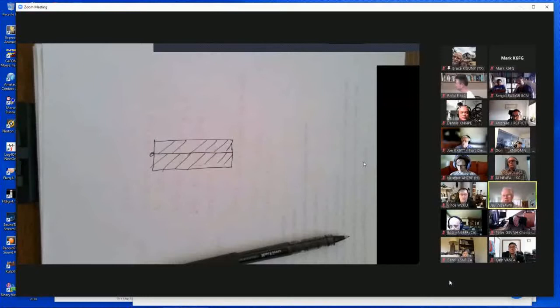There is another solution of Maxwell's equations which says your power will drop as the inverse. That is fine. If you want to do that, you need an antenna that is the size of the universe. In other words, it has to be almost infinitely long. There are people who have experimented over the years with this type of antenna, which is made up of a giant coil and a giant capacitor. It's designed to generate the E and H fields, the electromagnetic fields, separately, and then they combine together as they fly off into space. There's been some discussion as to whether or not that really works.